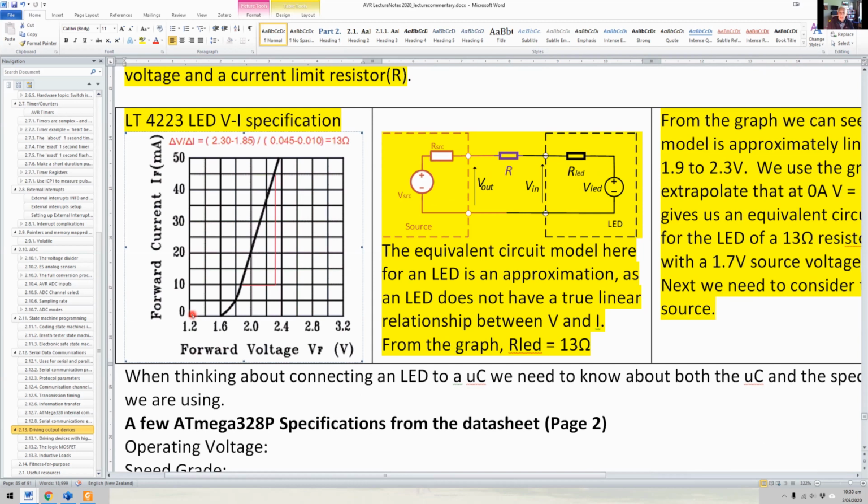Well, you know it glows. And we know that below a certain voltage it won't glow, and above a certain voltage it will blow up. So we're really only interested in this middle section of the graph. Looking at this, you can see that it almost appears like a resistance, because if we plot voltage against current for a resistor, we get a straight line from 0 going up. In this case, of course, we don't start at 0, we start at some other value. As long as our voltage stays within this range, we're going to get a nice linear transfer characteristic, where the current and the voltage are related by a straight line.